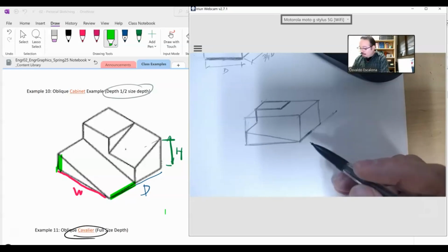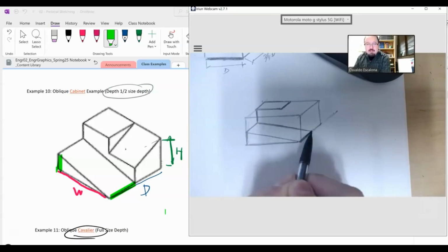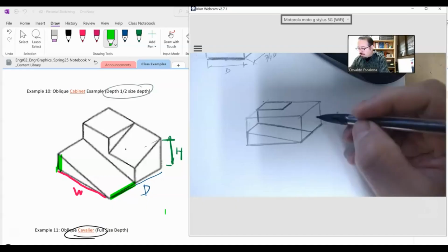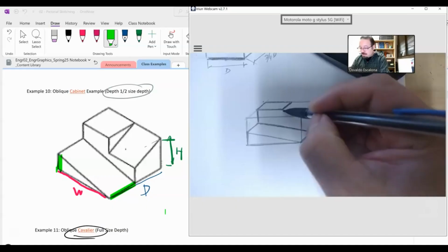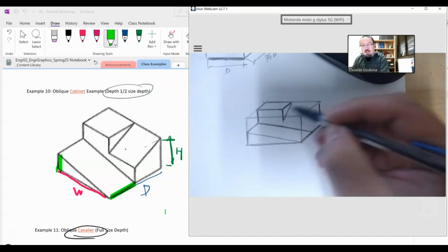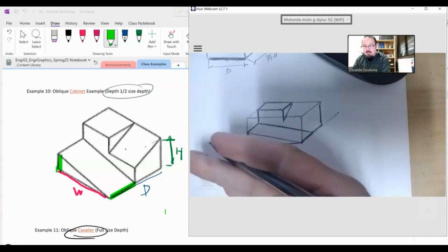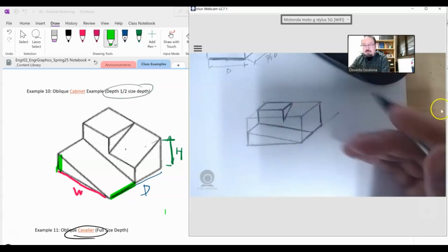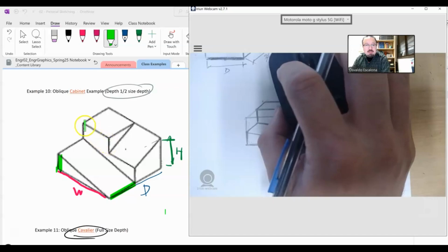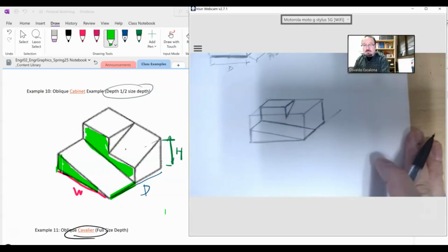The cabinet one. And then right after you do this, then you connect this one with that one. Somewhere about there, right? Then this one will continue upwards, this guy will go sideways, this guy will go downwards by the distance, it's the same distance, and then you will come about here, right? Remember, whatever I see in the front view, every view that is parallel will be a true size, okay? And because this guy is an isometric view, by the way, when you create your isometric views, whatever I'm drawing in green, in terms of the widths, would be a true size in your front view.